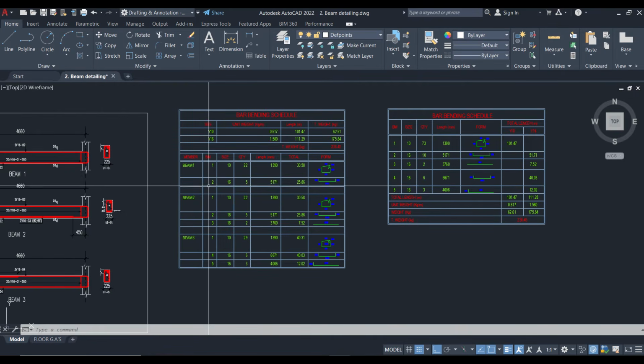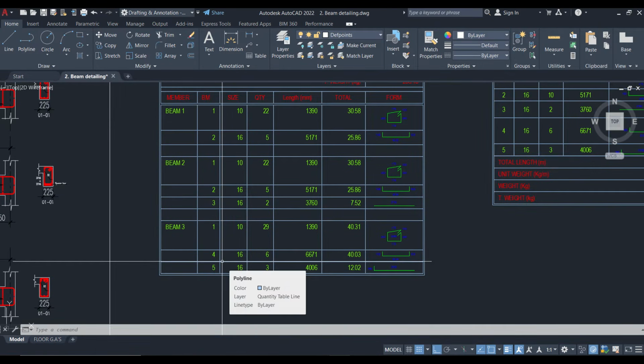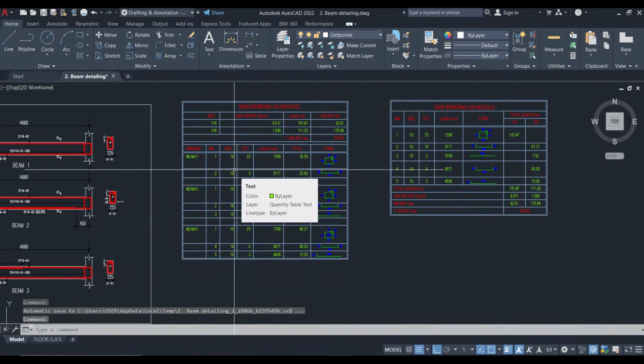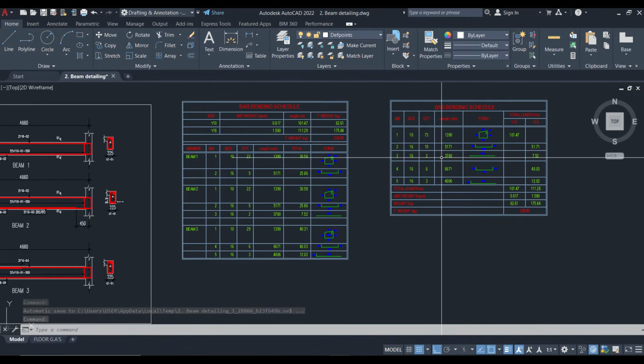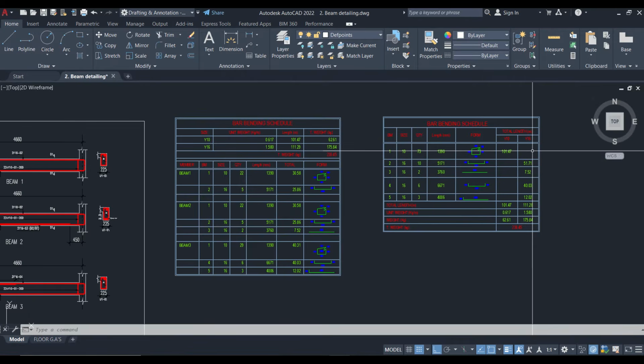But if you use the first method, we have 5 different types, but because there are repetitions in different members, we end up creating about 8 rows of reinforcement. So let's say we have 10 reinforcement, you can end up creating about 50 rows, and when you combine them together you are just having 20 rows. So this one reduces the amount of space, and it is much faster, but the disadvantage there is that it is prone to error because you can easily make mistakes in your additions and your subtractions.